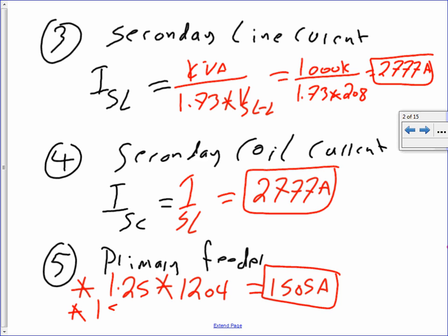So you take the 1505 amps divided by, did they do 7 here? Looks like 7 runs, divided by 7 runs, and that will give me 376 amps.